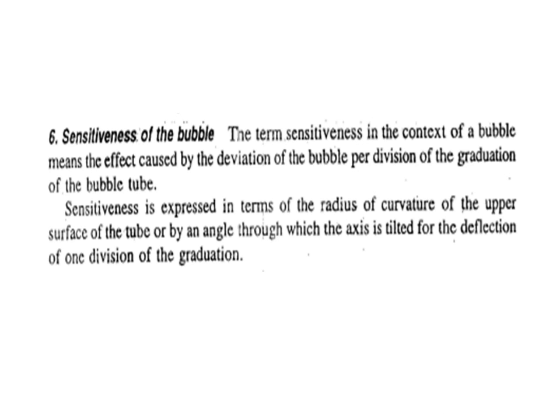For the long side, the curvature of Earth affects the staff reading. Therefore, the line of sight is horizontal, but the level line is curved and parallel to the mean spheroidal surface of Earth. So in the figure, the instrument is shown and two lines are shown. One represents the line of sight, which is horizontal, and another line shows the level line.